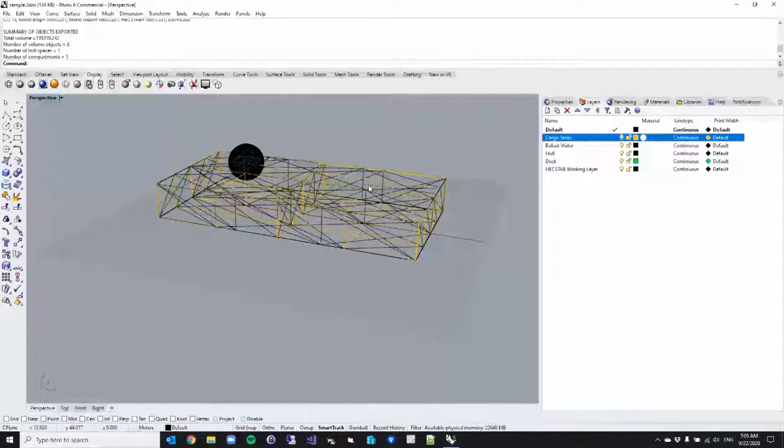We're also looking at tools like Grasshopper that would help automatically generate compartments, where you can visually, programmatically lay out how things are cut and how things are put together, and then have Grasshopper do that automatically. Even if you make drastic changes to your model, if you changed your overall hull, it could re-slice, recreate, and recut all of your internal subdivisions as well. So it's definitely something that we're focused on doing moving forward.